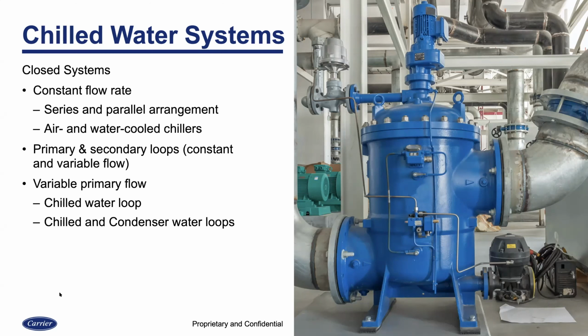Manifolded pumping is when the pumps discharge fluid to a header, and then from this header, water is supplied to the building. And this type of pumping configuration is usually applied to increase redundancy and also flexibility. And once again, this is a very high level introduction about chilled water systems and closed systems in particular.